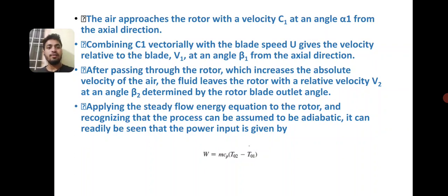Applying the steady flow energy equation to the rotor and recognizing that the process can be assumed to be adiabatic, it can readily be seen that the power input is given by W = m cp (T02 - T01).